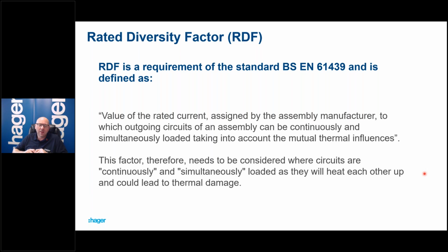So you need to consider it where circuits are continuously and simultaneously loaded, because they can heat each other up, which can lead to thermal damage. It can also lead to unwanted operation. If you remember back where we had the solar PV that was constantly loaded, to stop it being simultaneously loaded with another load, I put a blank in there, didn't I, on the demonstration?